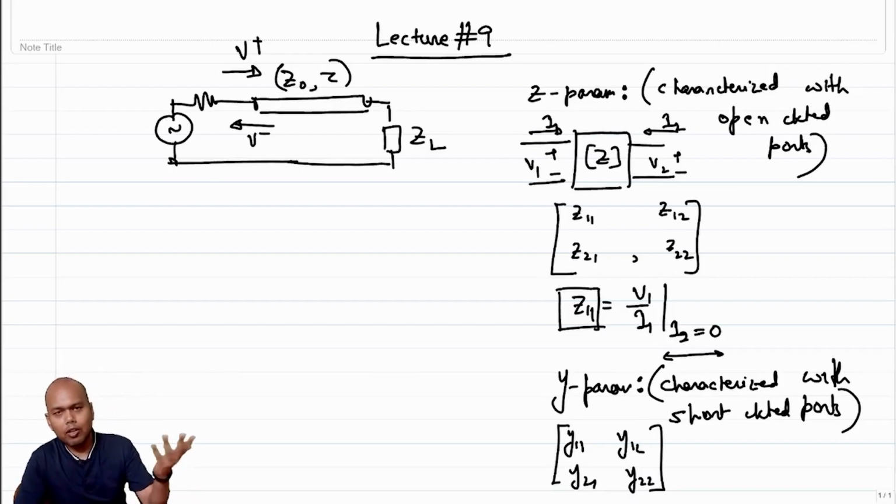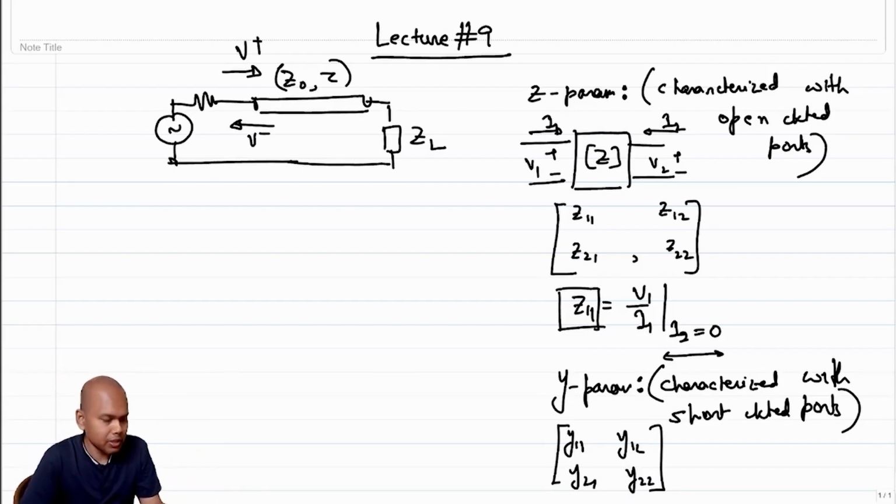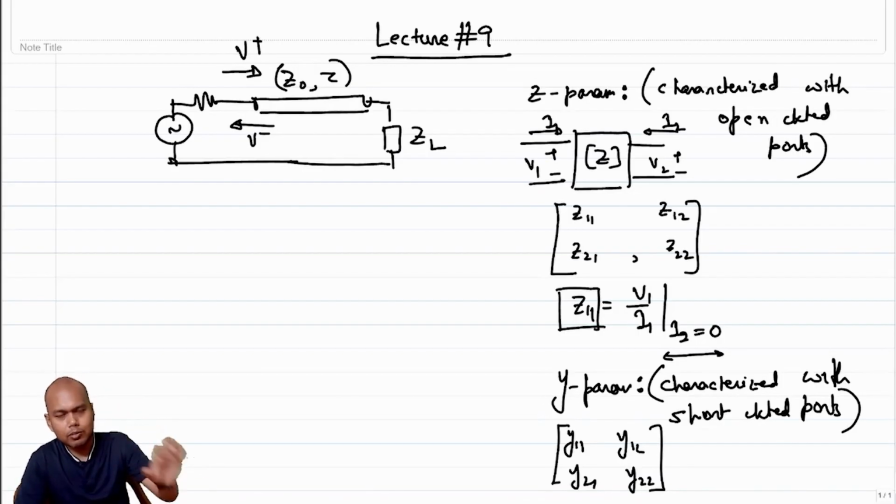And if you want to open circuit, the port will terminate somewhere, both the terminals will terminate somewhere, and the moment you terminate it with anything, you are going to have a capacitance between those two terminals, right? Those capacitances and those inductances are always present, but their effects are more visible at higher frequencies than lower frequencies, right?